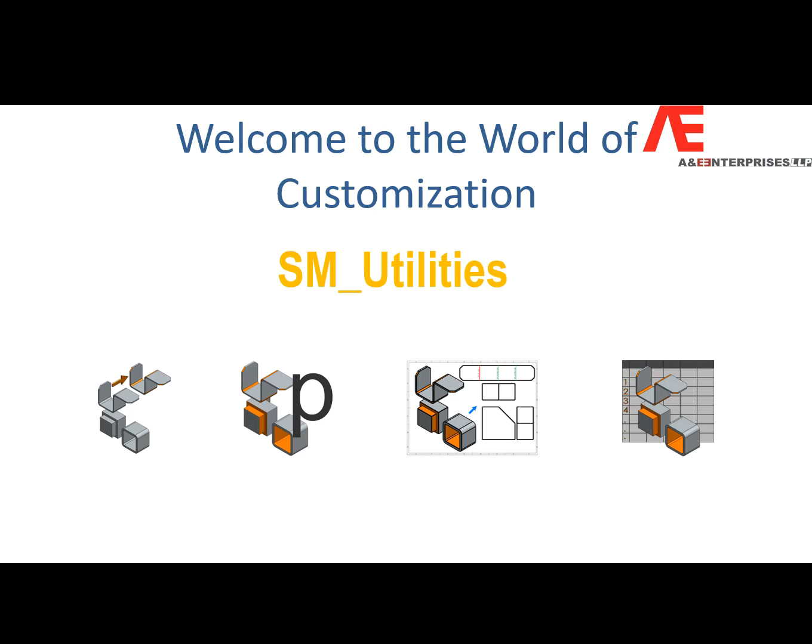You also have to export a bill of material which shows how many components there are, which are sheet metal components, which are non-sheet metal components, and all the parameters which belong to these components. If it is a sheet metal component, what are the parameters you want to export? The format can be decided, but the typical data would be thickness of the sheet, bounding box area, blank area, number of bends. If you require it, for every bend, the bend parameters like bend distance, bend angle, bend radius, and the direction.